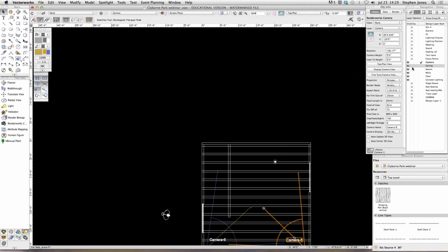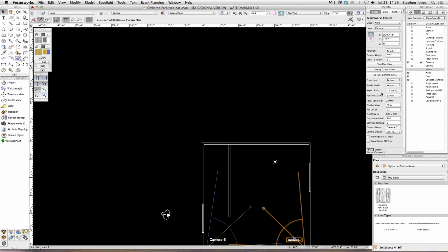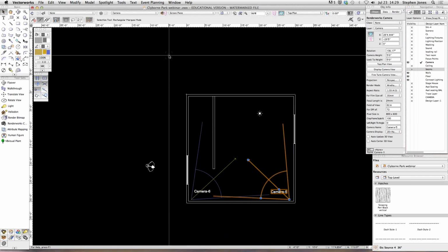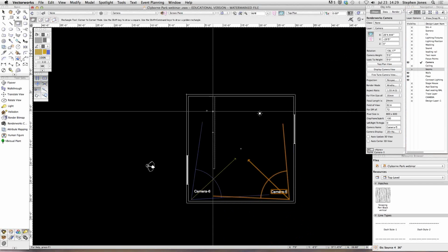So we're going to start by turning off, in our navigation window here, the ceiling, and we're going to turn off the beams for the moment, and we're going to create our own custom lighting source that's going to give us soft area lighting. Now this applies to any three-dimensional object that you can apply textures to. I should really point that out.